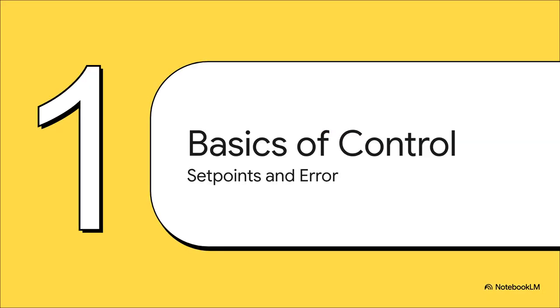Section 1. The basics of process control. Understanding set points and error. All right, the absolutely crucial point here is that control action only happens when there's an error. And what's an error? It's just the simple difference between what we want, which is our set point, and what we actually have right now, our measured quantity. In a closed-loop feedback system like this, an error literally has to occur before any corrective action is taken.